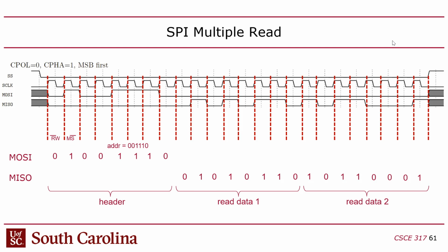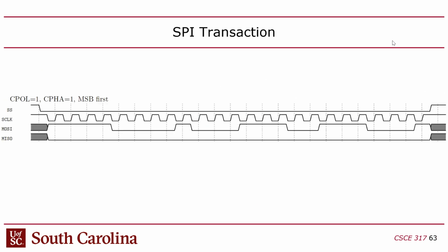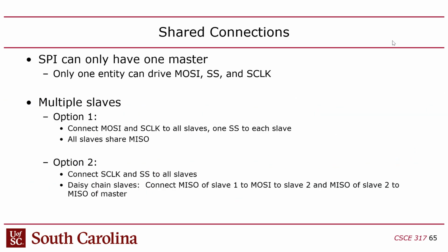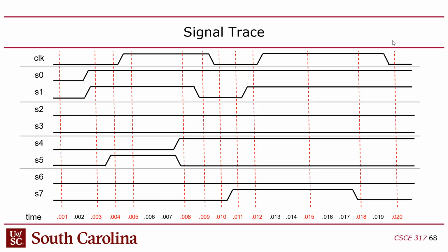And if we take the length of the transaction in terms of clock cycles and divide it by 8, that will give us the number of exchanges. And then if we subtract 1 from that number, that will be the number of bytes that we read. Now, I talked last lecture about how in Lab 1 we have a little different way to handle that, and I'll get to that shortly. So, in fact, I'll talk about that now.